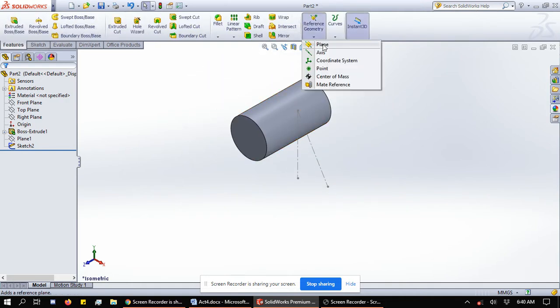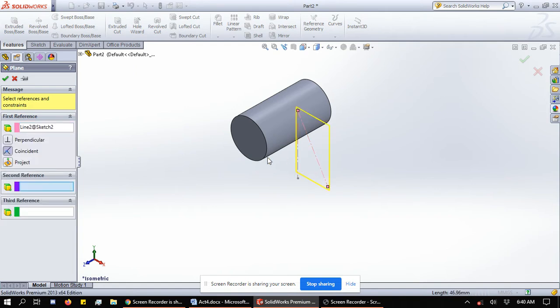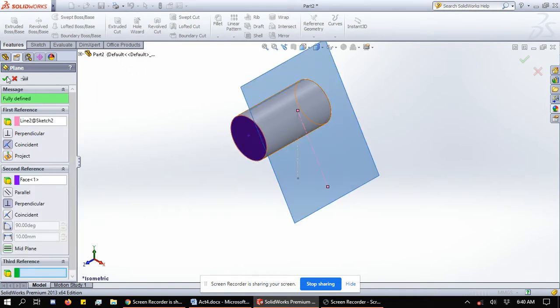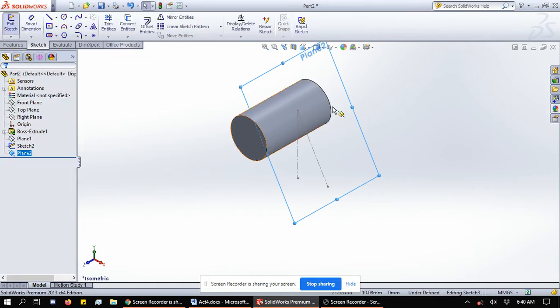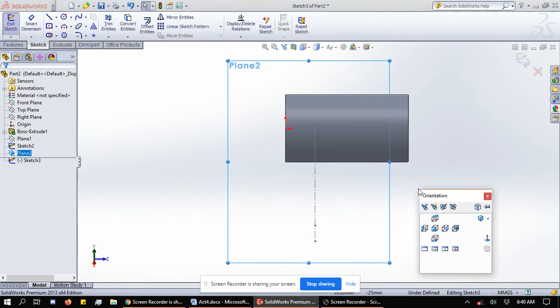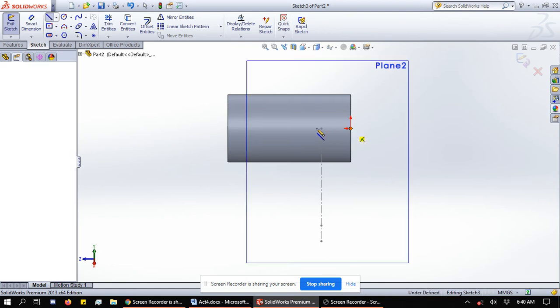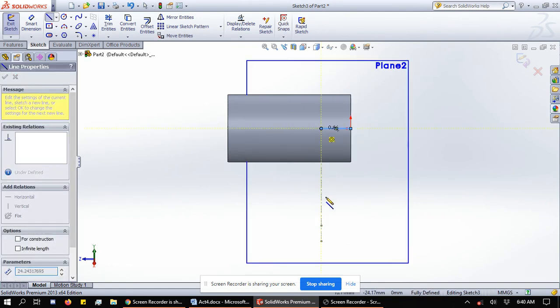And we are going to create another reference plane by just clicking this line and this face, the front plane. Either of the two is okay. So check. Then we sketch on it, click on the plane, and normal to. Now we create a line. This needs to be 12, and this any measurement first. Same as here, here, here, and here.